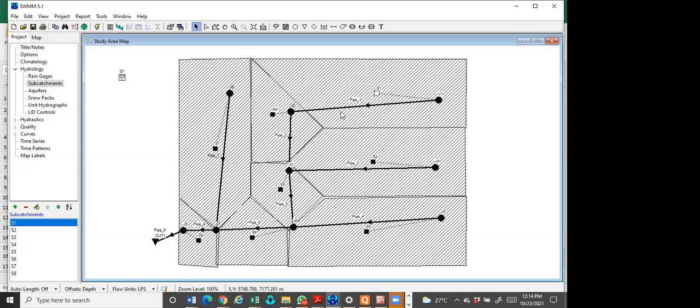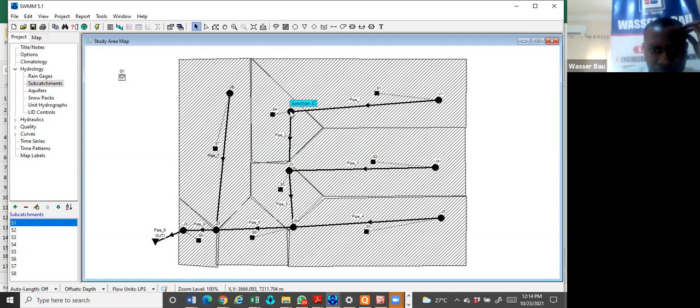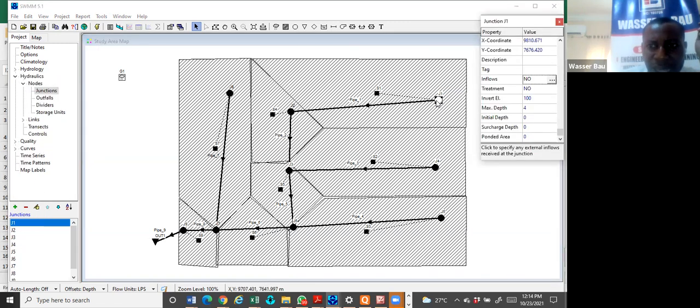Are we together? So can I give us another 5 minutes for us to design the elevation. What I did here is 100. Since the slope is 0.5%, here will automatically be 97.5, because 0.005 of 500 meter length means after 500 meters, I have gone down by 2.5 meters.